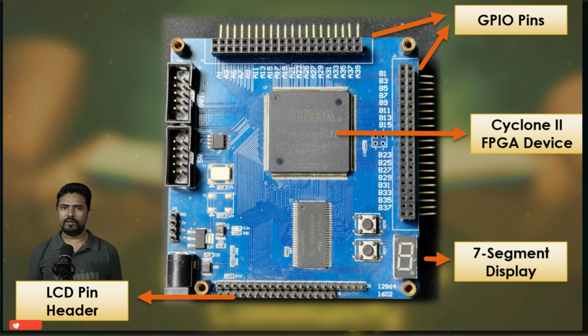Additionally, I will demonstrate how to use the USB Blaster to program the FPGA. This is particularly useful for testing purposes right after compiling your projects on the development board. We will also explore some of the output reports of the Quartus packages, including the netlist viewer. This tool is quite useful because it allows you to see the hardware realization in your design.